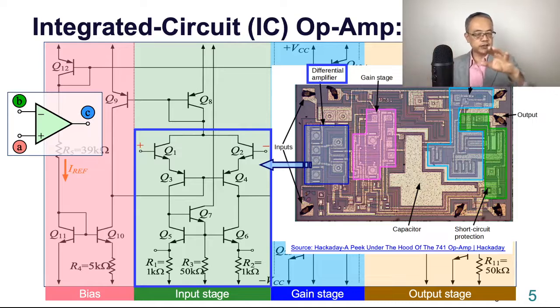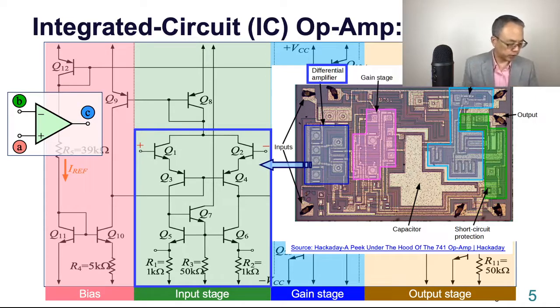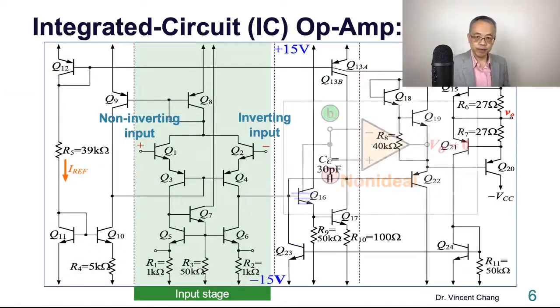I will teach this in a fundamental analog electrical circuit course and try to solve the input offset voltage for a differential amplifier. In that case, I will assume device mismatch or load mismatch, because of the mismatch between the two sides of the input differential amplifier. So two reasons. Number one is systematic offset. The other one is the mismatch of the differential amplifier.